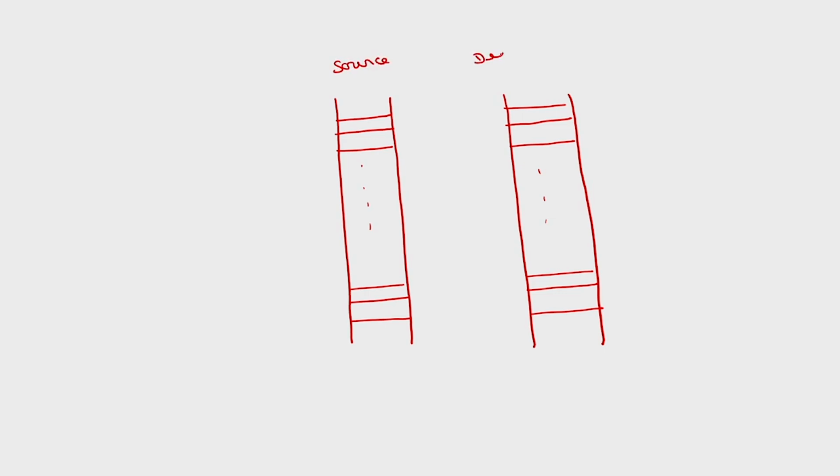This is source and destination, same example, but here the number transferred is 100 words, because I have written move string word and I have loaded CX with 0064H, then I have cleared the direction flag. So, 100 words has to be transferred. So, 100 words is 100 decimal, 100 words is equal to 200 bytes. In hexadecimal, what is this 200 bytes? 100 is equivalent to 64.